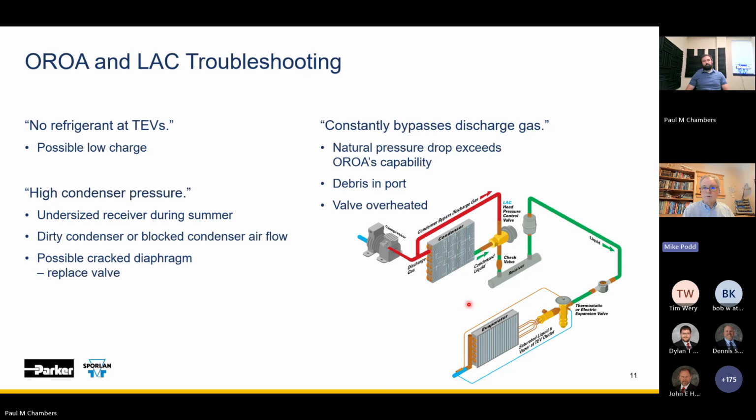40% of that condenser is already flooded. So if I only need 80% of my condenser flooded, I'm already at 40. I only need to add 40% of the total flooded charge to get back where I need to be. Make sense? I covered a lot in a sentence there. Sorry, I think we're running up on time, but that's that charge thing.